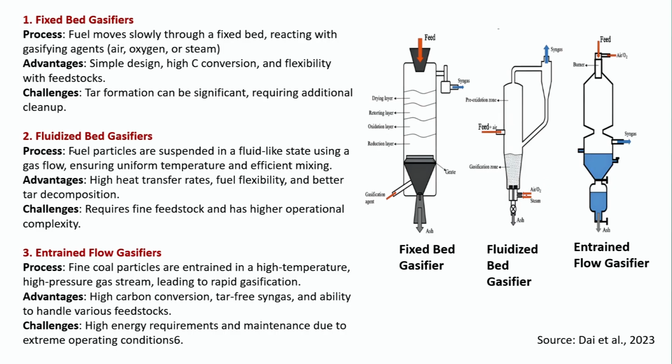You get high heat transfer rates, fuel flexibility, and better tar decomposition, which is very important. Once your material is put into this bed, it is not going to be similar to the fixed bed gasifier, where you have issues with tar and need cleaning up mechanisms.